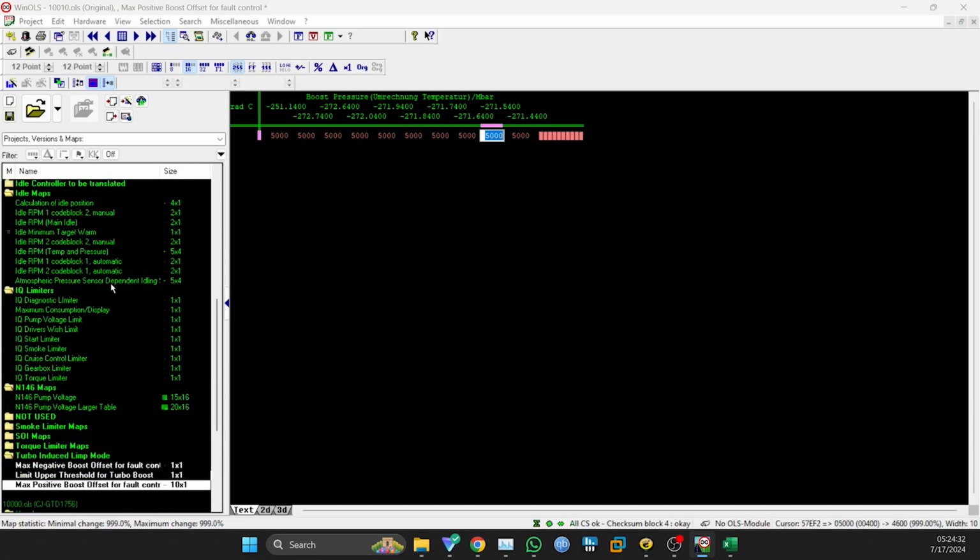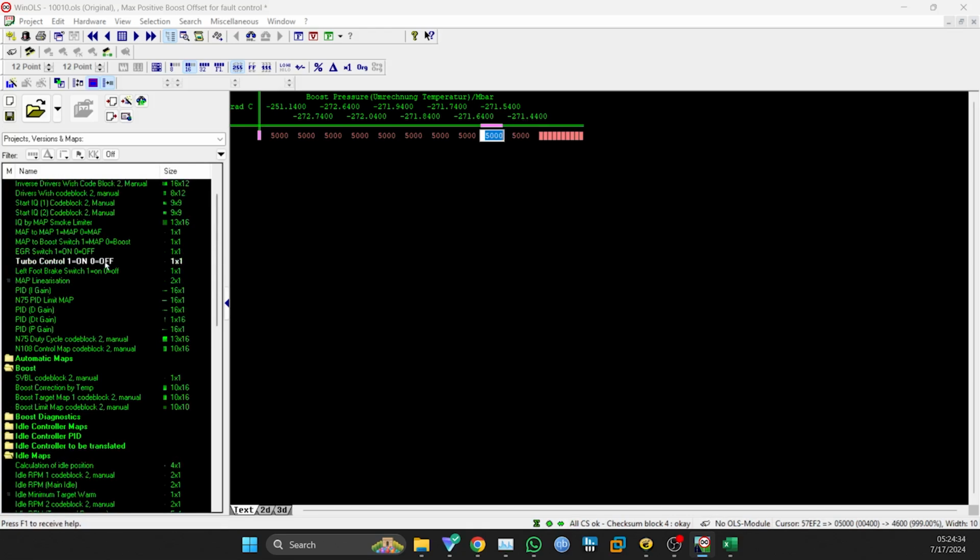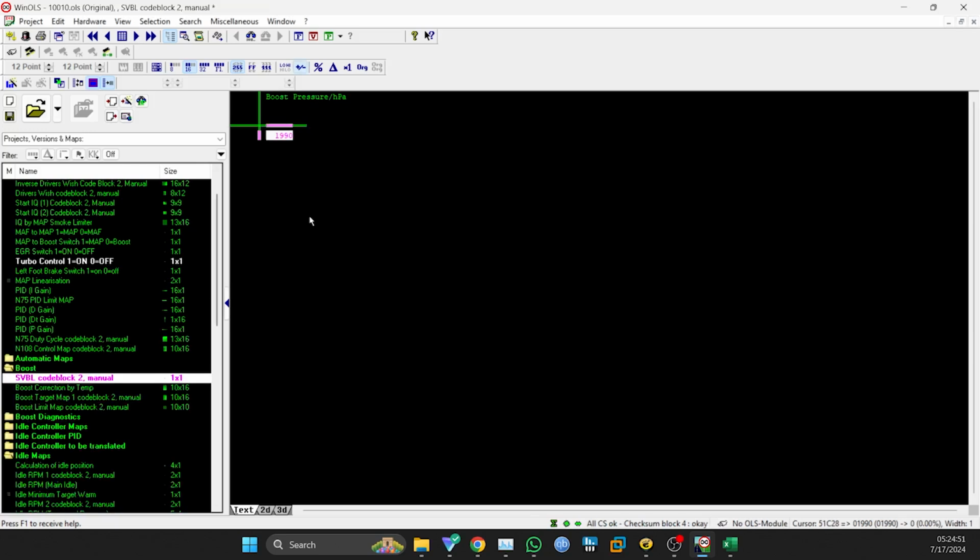All right, so right now we're set up for wastegate control. That being said, the N75 code will still be present if you don't leave it plugged in. Again, go back to the video that I did showing you how to delete the codes inside the ECU. Do the same thing. I don't believe this is necessary, but if we want, we can change this to 8,000 as well.